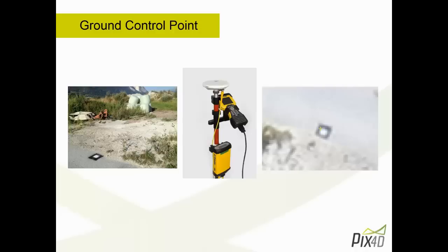All right, so let's start with the simple question. What's a ground control point? In most cases, a ground control point is basically a marking on the ground measured by a high precision GPS. Then you acquire your imagery using your UAV or your drone of this area where you marked this GCP on the ground. And just before processing, you include the measurement you did with your GPS inside of the project to enhance the georeferencing and the accuracy.